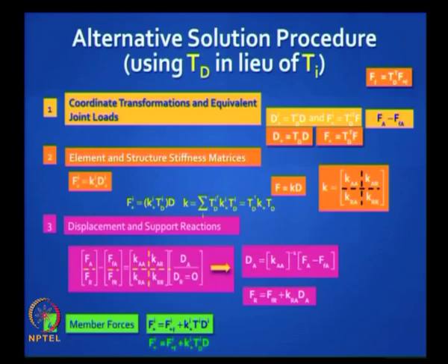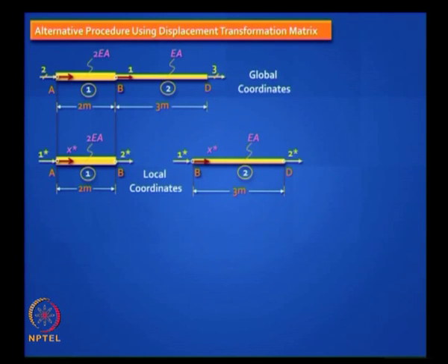So the size of di will be how much for an axial system element? No, that's for a plane truss element. For an axial element, 1D element, it's 2 by 2, okay. But here you don't have to worry about selecting those values, you can directly deal with the D vector of the global structure. Okay, you will understand this as we work. So let's do this together.